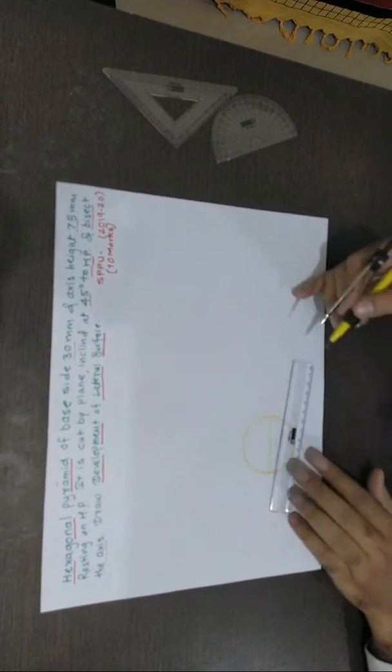So you got these 2 points. Now keep the leg of your compass on one end of the diameter what you've drawn. Draw the arc on both the sides and repeat the procedure here also. So circle, draw horizontal diameter, so these 2 points, and from this point mark an arc equal to the same radius which is the side of hexagon, and mark the arc this and this. Now join all those points, that's your hexagon.